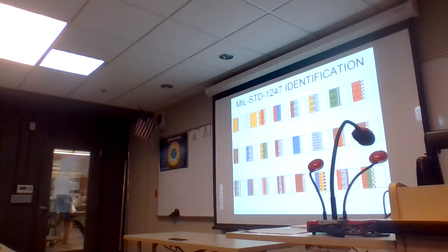The symbology that they use is always a black circle on a white background, and they've got the word hydraulic. So for people that can't speak English, for people that are colorblind, and for people that can only understand symbols, I guess we've provided three different methods of identification for those systems. The symbology, regardless of system, will always be a black symbol on a white background. That, by the way, is the answer to an FAA test question. So a black symbol on a white background.